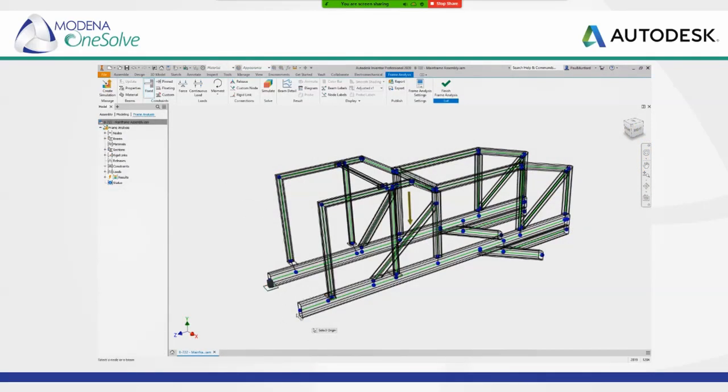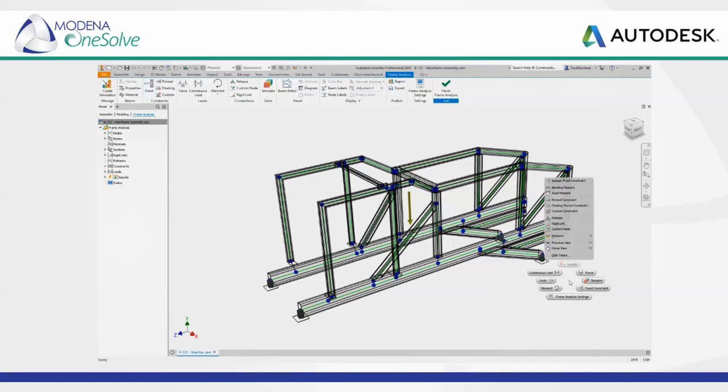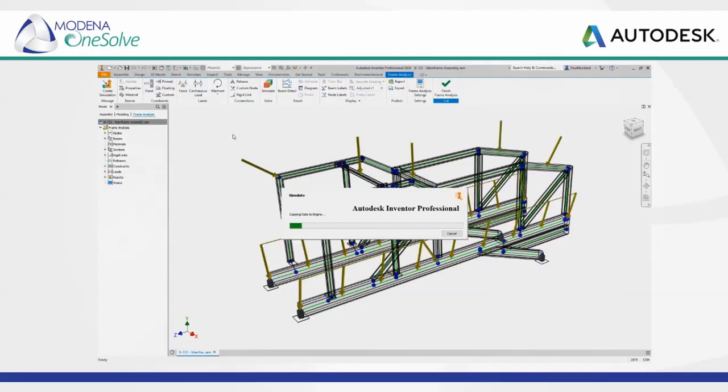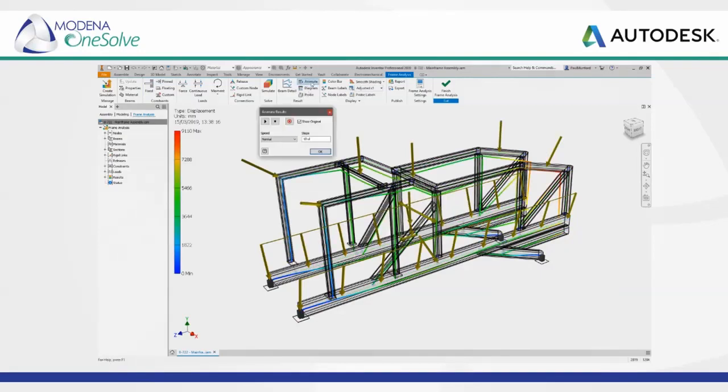The standardized nature of frame design also makes it easy to set up and perform structural analysis to make sure your design performs as required. Just add your constraints, for example where the frame is fixed to the floor, and you can start specifying where the loads will be applied. Loads could be applied as point forces, axial moments, or continuous loads across the length of the frame members. The solve time for frame analysis is super quick, so you can immediately begin reviewing displacement and stress results to determine if further design refinement is required.